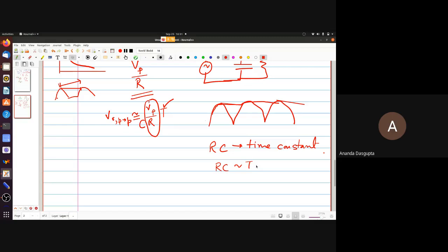Just for a quick estimate, what's the time period for the AC source that we have, the AC mains? How much is the time period? 1 by 50. Yeah, 1 by 50, but how much is that? That's 20 milliseconds, right? It is 1/50th of a second, but that's 20 milliseconds. If R times C is 1 second, then 20 milliseconds is very small compared to that. Then your ripple will be rather small, which is the kind of thing that you're aiming at.